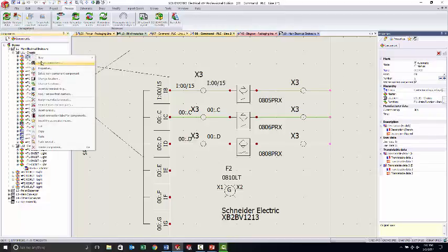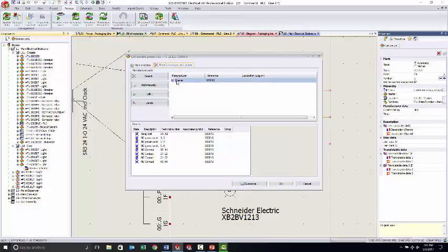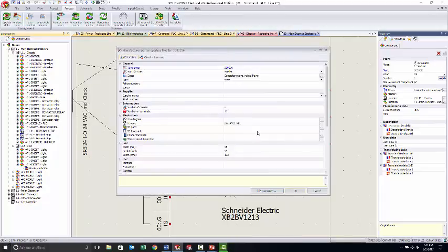All right, now this component, if I added it here, but what I can do in that part in the library before I even create this. So let me go into my properties here and look at that manufacturer. So if I edit this, I can do a couple of things in the library. One of them is create that symbol that it is going to use automatically for that main manufacturer. I can do the same thing with the 2D footprint so that it's automatically going to grab that.